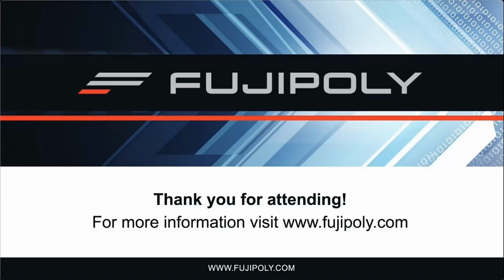And then next question, my application has a non-silicon requirement. Do you have any dispensable materials for this? So if your application has a gap in it, then we can suggest the SPG dispensable TIMs. They are made of silicon, but they are tested for low outgas, and that's as per the ASTM E595 standard.